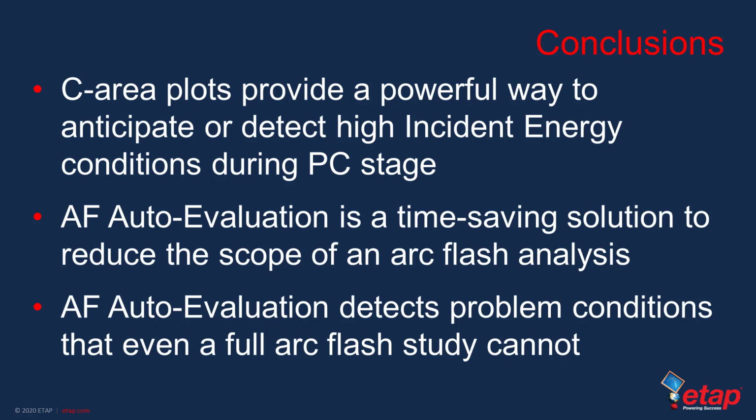This is perhaps the most important value because we do not have to wait until we get to an arc flash analysis study to detect high incident energy conditions, but we can address most of them during the settings selection for our protective devices. We have also observed during the presentation that arc flash auto evaluation is a time-saving solution, which significantly reduces the scope of an arc flash analysis.